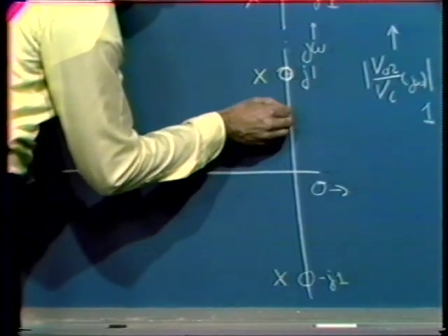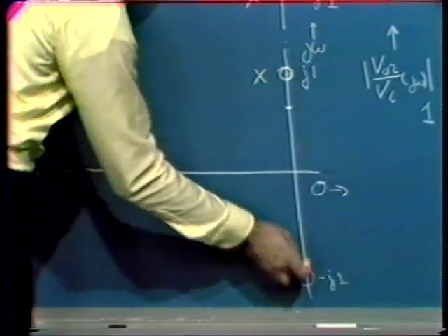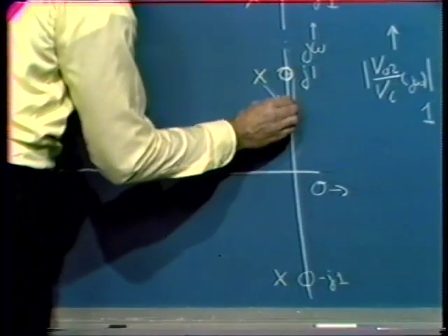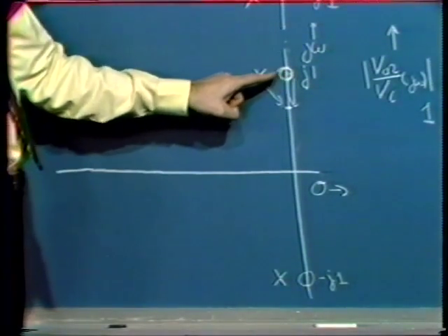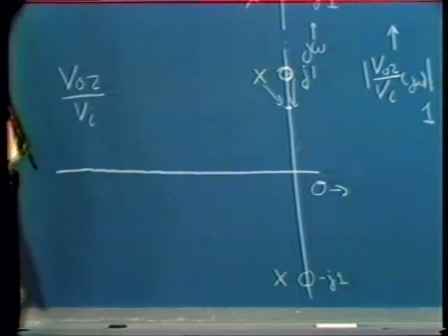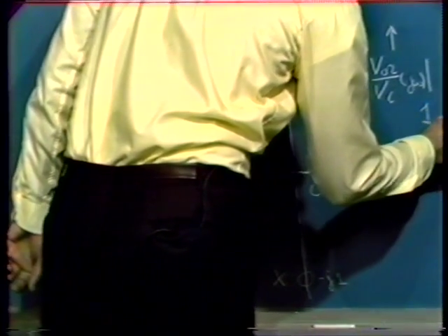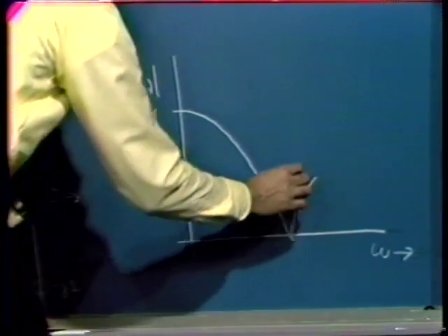However, if we're even slightly displaced from that point, these two vectors just about cancel, these two vectors just about cancel. And so the gain of this network is the same at almost all frequencies, except in the immediate vicinity of the 0. And of course, at the 0, the response must go to 0. So here we'd anticipate a rejection amplifier where the response really goes to 0 at 1 radian per second.